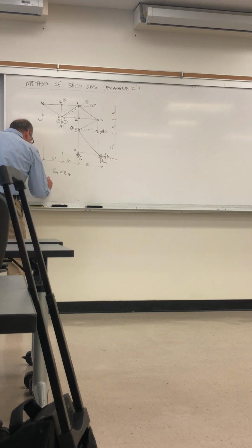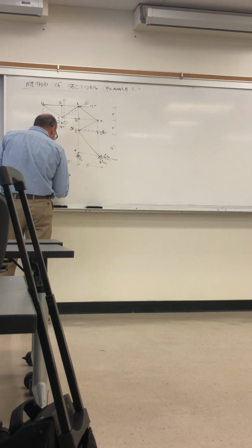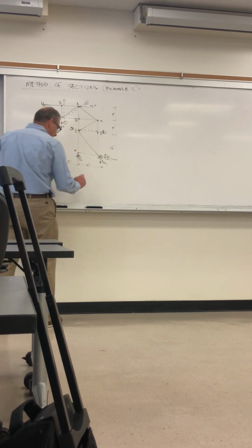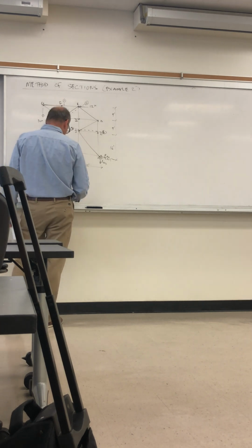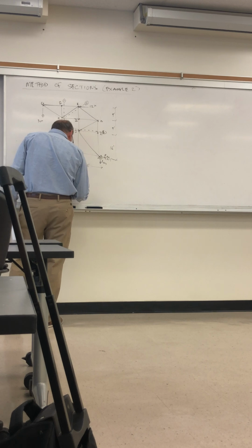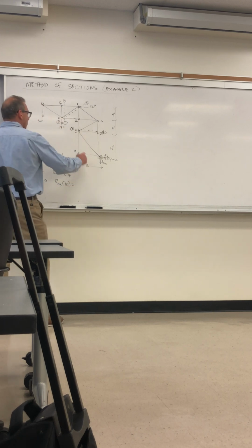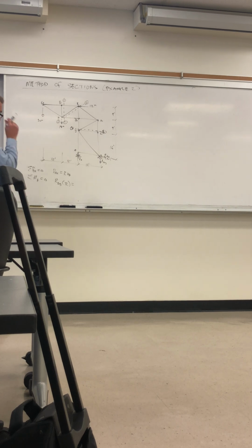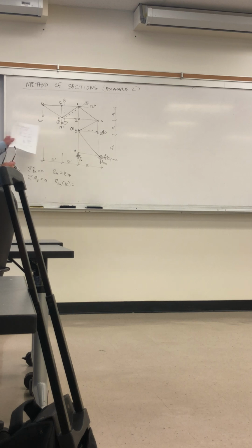So I have R_CBY multiplied by 12. So that's a clockwise moment at A equals the 3 contributions to the moment going counterclockwise from the 3 applied forces.